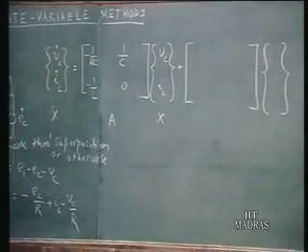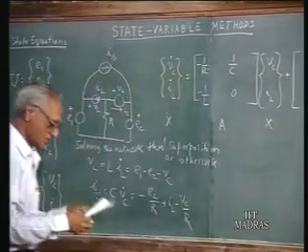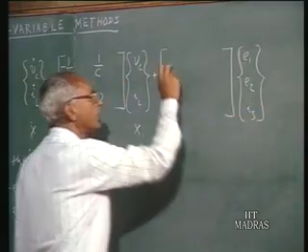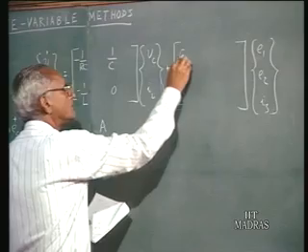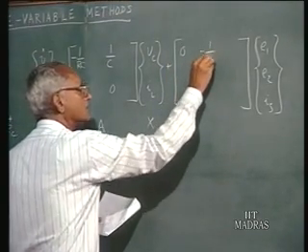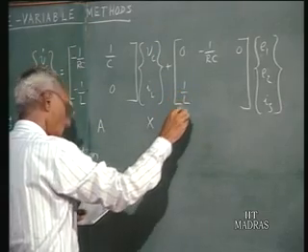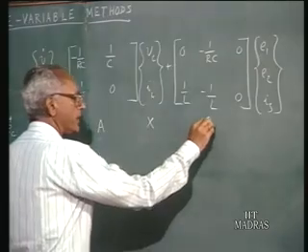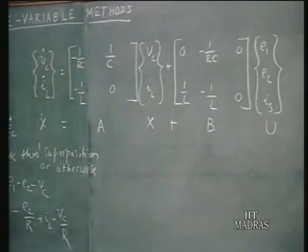U is the input vector which has 3 quantities, E1, E2 and IS. So we have to write E1, E2 and IS. And we have 3 columns here therefore, and that would turn out to be 0, minus 1 by RC, 0, 1 by L, minus 1 by L and 0. That is B. So X dot equals AX plus BU, that equation has been established.